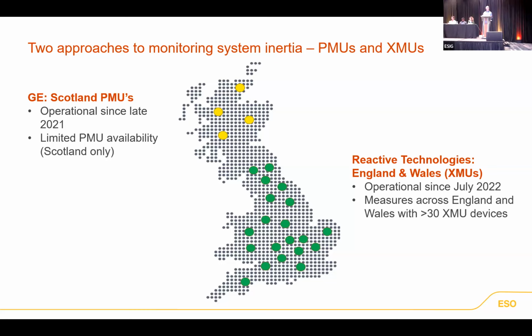Because this is new, we went with two different technologies. We were using a GE technology in Scotland, which is using PMU data and the SCADA system in order to see what is on the system and then doing a calculation as to what the inertia is. We're also using the Reactive Technologies solution, which is a 10 MVA supercharged capacitor located in Teesside in the northeast of England that pulses the 10 MVA charge onto the system at very precisely timed sequencing.